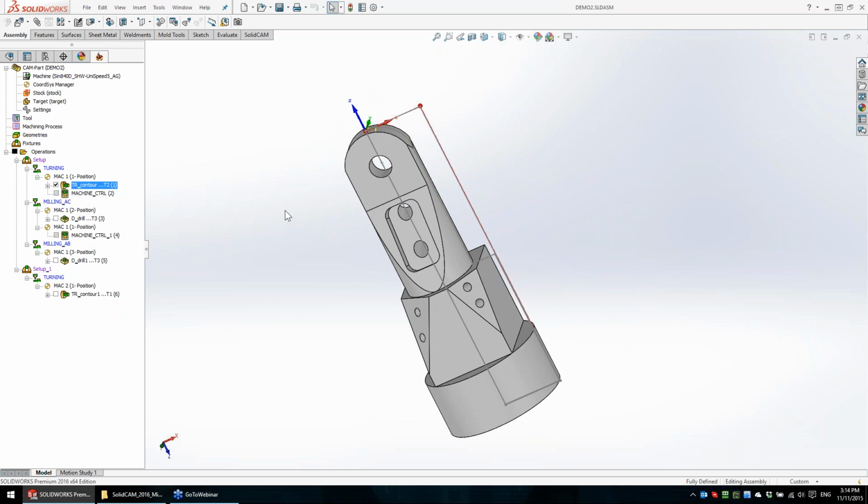on this machine, because we have 3 rotary axes, but in an operation we can use only 5: 3 linear and 2 rotary axes. One rotary axis will always remain not used. We call it a non-kinematic axis. The axes that are used in the operation are kinematic. The 6th axis is not a kinematic axis. So this non-kinematic axis, we need to control it with a machine control operation.